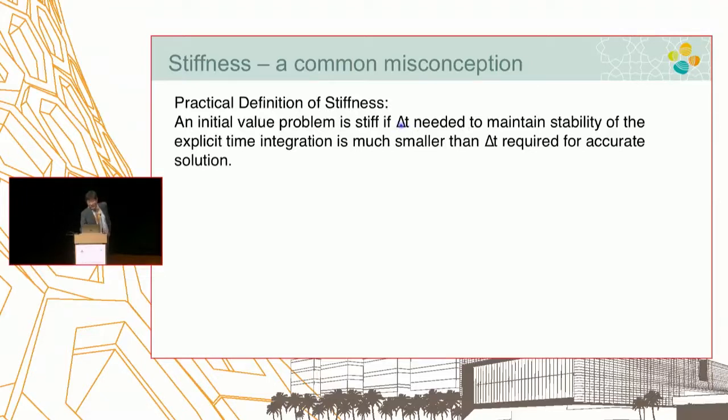If the delta t needed to maintain stability is much smaller than what I need for the science investigation, that's the stiffness problem. Otherwise, it is wrong to call the problem stiff. It is the time scale you need to resolve to ensure an accurate solution. Many people get confused about that. Just because you have a huge dynamic range doesn't mean it's a stiff system. It's just a computationally demanding problem. The nanoscale has to be resolved if that is important for your physics.